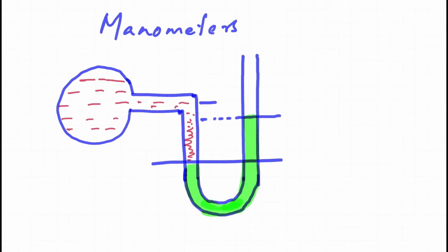So I have shown a couple of lengths here. One is the height of the vertical column on the right hand side, and next is the height to the center of the pipe. So I'm going to call them X and Y, and we have a pressure within the pipe, and we also have atmospheric pressure acting on the top of the right hand side pressure column.